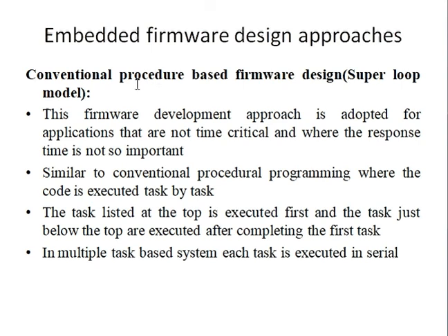In conventional procedure based firmware design, you're not going to use any operating system. Why would you use this kind of firmware? It will be advantageous when you don't expect the response time from the peripherals to be very quick. For example, consider the calculator itself.